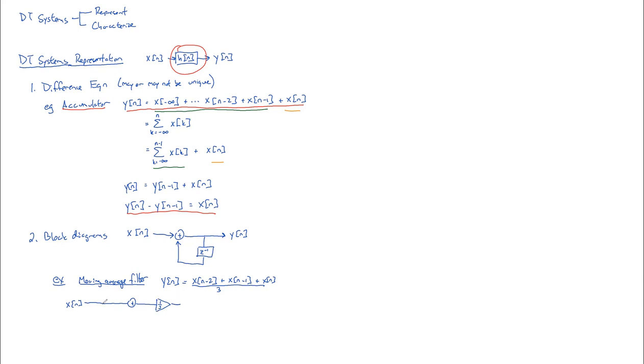And then we're going to have to delay that by 1, and I'm going to delay the delayed version by another one. So this will be delayed by 2. And that's a block diagram of a length 3 moving average filter. And so, sir, those will never really be like z to the negative 2 to show going back twice. You'll just have one go into another.